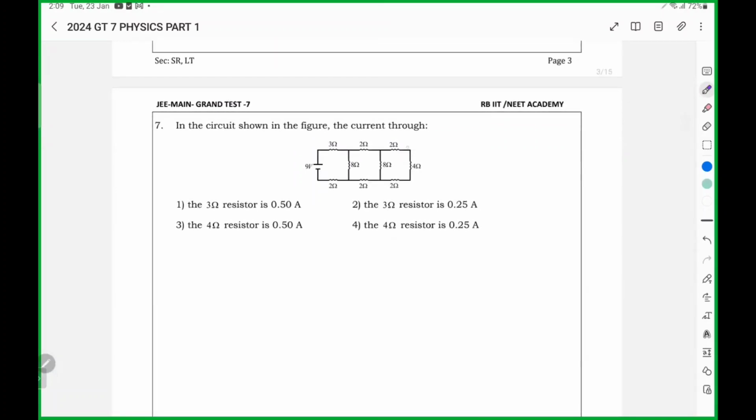Here in this circuit, these three are in series. So here 8 ohms, and here again 8 ohms. These two are in parallel. The effective resistance becomes 4 ohms, that is R1 R2 by R1 plus R2, 64 by 16.